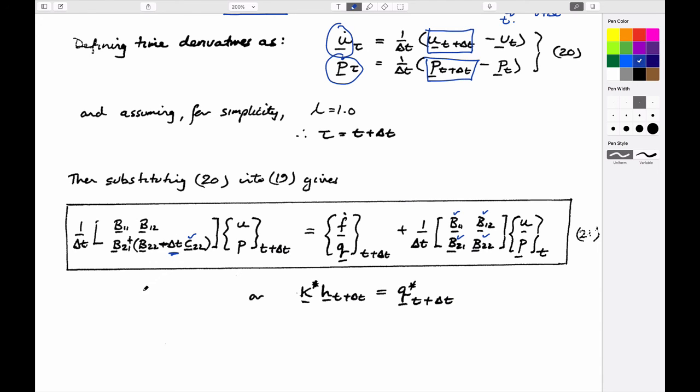We choose a time step, and we know something about the initial conditions at time 0, what the displacements are and what the pore fluid pressures are. And we define these in terms of our appropriate conditions. The only thing that's a little strange here is that if we have a flow condition described, most of these Q values are 0. If they're internal nodes, the stuff that comes out of one element has to go into the other element. And so internal values of Q are equal to 0.